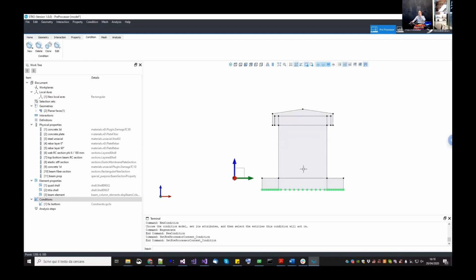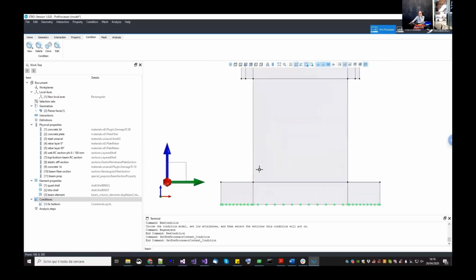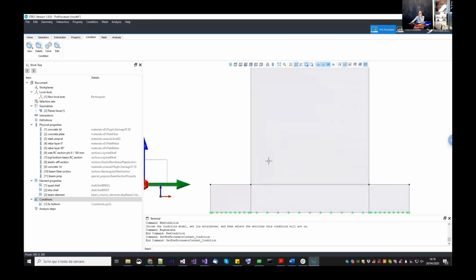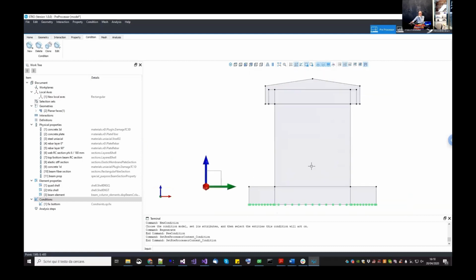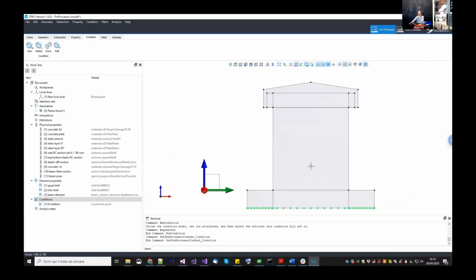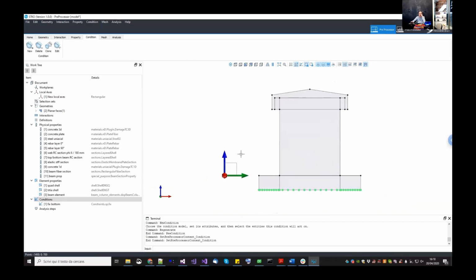So if you're using OpenSees manually, the only option that you have is to do nodal lumping manually and to assign equivalent nodal forces all over the mesh. Now you understand that this is not so easy. You need to create your own scripts. They will work with some elements, but not with others. So it's very annoying. In STKO instead, it looks like there is this kind of distributed load, but it is not true, basically.